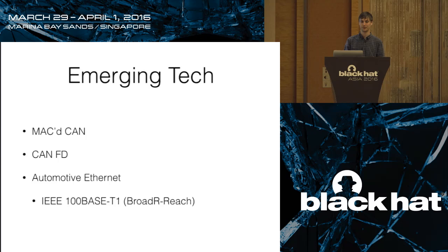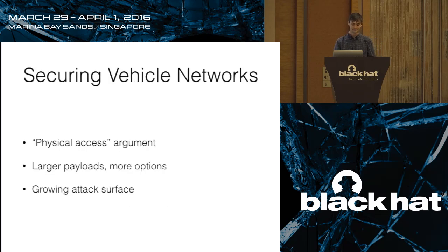In order to work with a computer, you're going to need a media converter. So that actually converts this 2-wire Ethernet to your traditional 4-wire. This computer doesn't have an Ethernet port, but most do. You can plug that right in. Those media converters are still quite expensive, so that's one new place where it's like, hey, that would be a useful thing to have, low-cost media converters. And also, we'll have to start looking at the protocols they use on Ethernet.